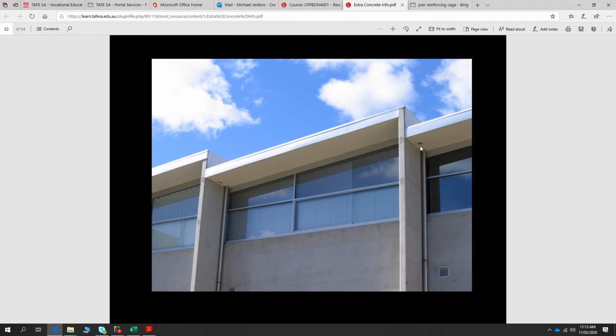That's your very neat way of doing it. Then typically at the top of your panel, you just use that steel angle there because you want something for fixing your roof too, and that makes a really nice, easy place for fixing any horizontal members too. But then at that point, it's not visible, people aren't kicking it, forklifts aren't running into it, etc.